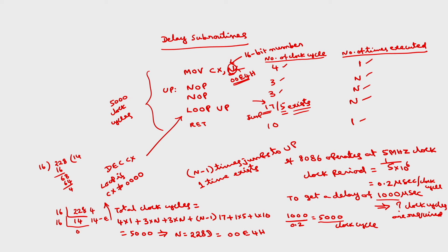Okay. So, this is about simple interfacing of an output device such as LED or CRO. So, you can generate a square wave of any desired frequency using 8086 and 8255. Similarly, you can blink the LED at any desired rate. Similarly, you can connect a switch also, an input device. So, I have discussed the output device. Now, I want to connect an input device to the 8086.